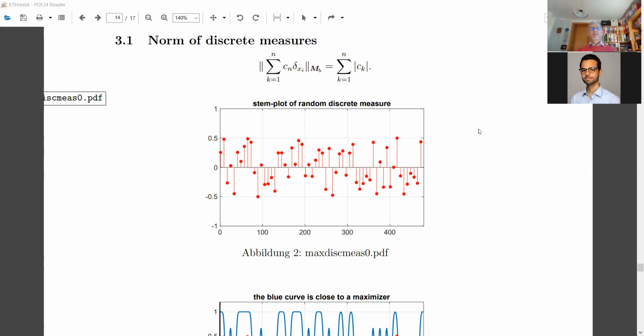So the first thing I'm showing you is a representation of a finite discrete signal. So I'm using the stem function. I just was using an arbitrary grid. So you see I'm taking signals of length 480. Later we will use it as a periodic, discrete signal. And then I took a sampling distance of 10. So I was placing random values between -1/2 and +1/2. So the range of the values is 1, but it's symmetrically arranged around 0. I think that's better than only taking positive values.